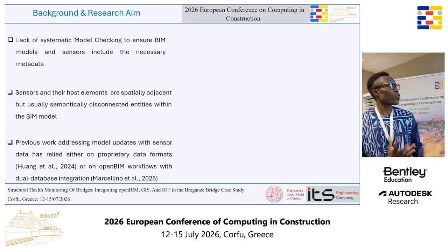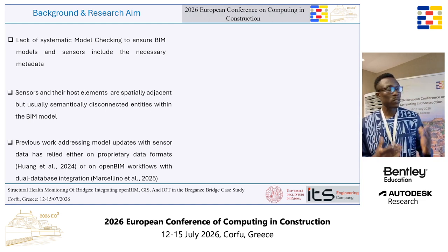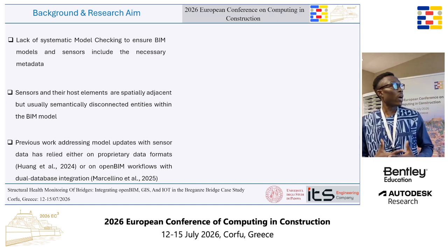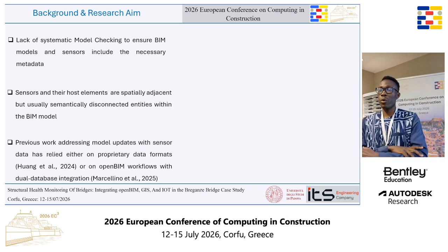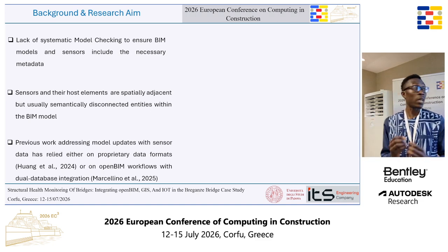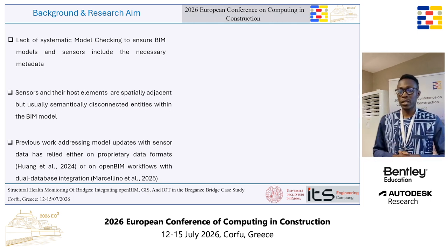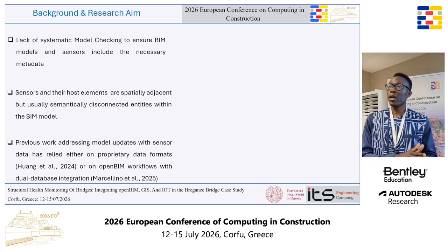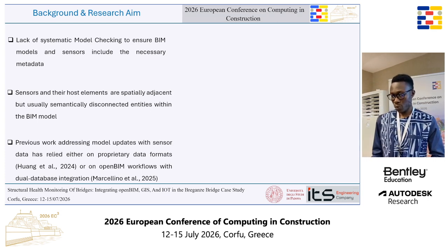While integrating structural health monitoring with bridge information modeling, we found that it often lacks metadata validation within the BIM model and also for the sensors inside the BIM model. Additionally, the sensor and the host element are usually close in the model, but are disconnected entities. And finally, when we look at previous work addressing the model update, they use either a proprietary data format or an OpenBIM workflow using dual database integration.